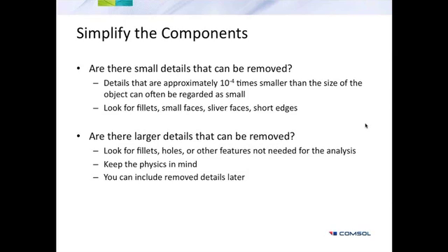Now, usually details that are very small, you can always remove, because they would not be resolved to enough accuracy by the mesher anyway, unless you really have a very large mesh. And by small in this sense, I mean things that are about 10,000 times smaller than what you're studying, what